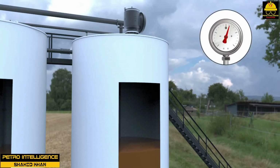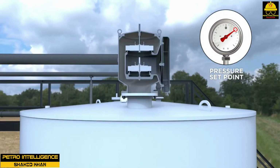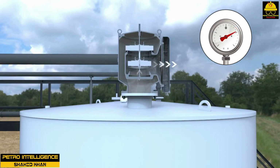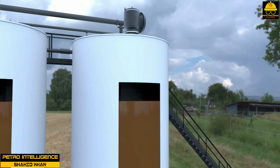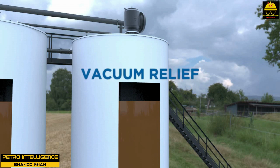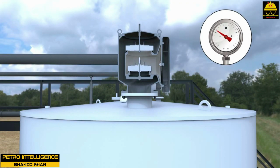Flame arresters. In tanks that store flammable materials, the vapor expelled by filling or heating is sometimes mixed with air, oxygen, in the proper proportions to be ignited. The vents are equipped with a flame arrestor to prevent the possibility of fire reaching the contents of the tank. Flame arresters are not designed to prevent flame passage indefinitely, and it is important to extinguish any fire at a flame arrestor immediately. Since the small passages in a flame arrestor element may plug from corrosion or foreign objects, the elements are cleaned on a regular schedule.